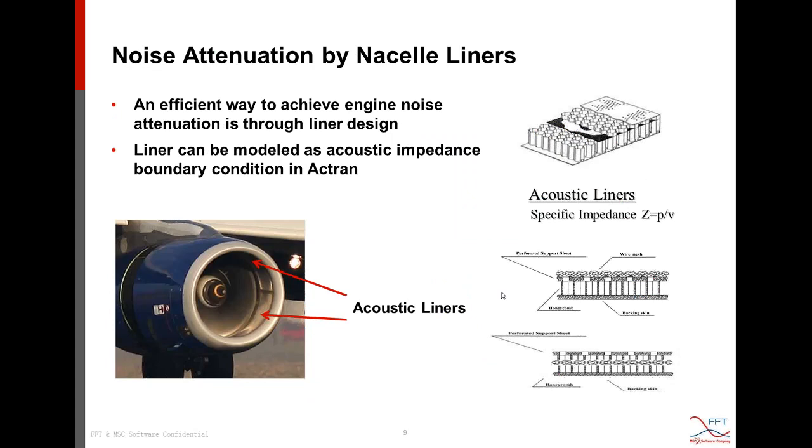Okay, so once we have the source definition, either analytical or numerical, we'll be able to propagate these sources in the finite element mesh and design the liner impedance that will absorb these sources in order to achieve acoustic attenuation.